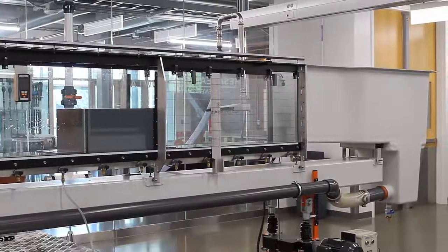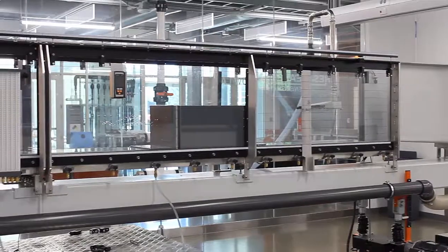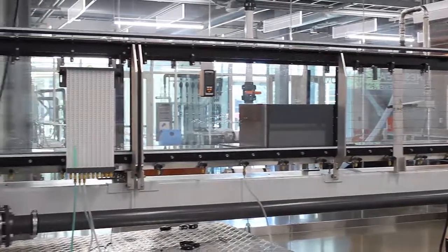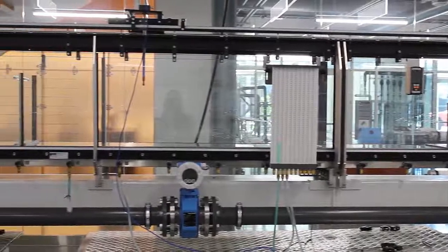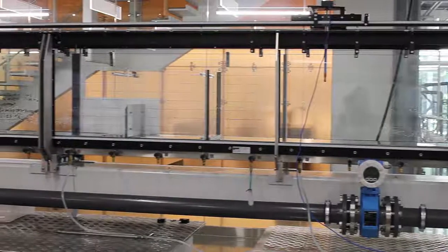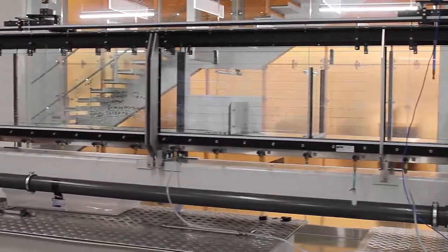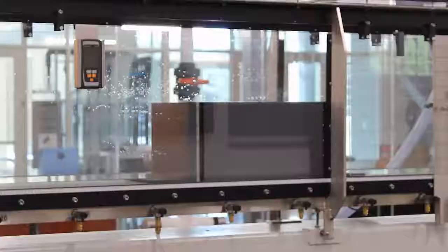In this experiment, our goal is to develop the weir discharge rating curve for 3 different weirs and compare the weir coefficients. In the experiment, we have 2 weirs sitting in the flume. The broad crest weir is near the inlet. The sharp crest weir is at the center, which will later be switched to the ogee-shaped weir.